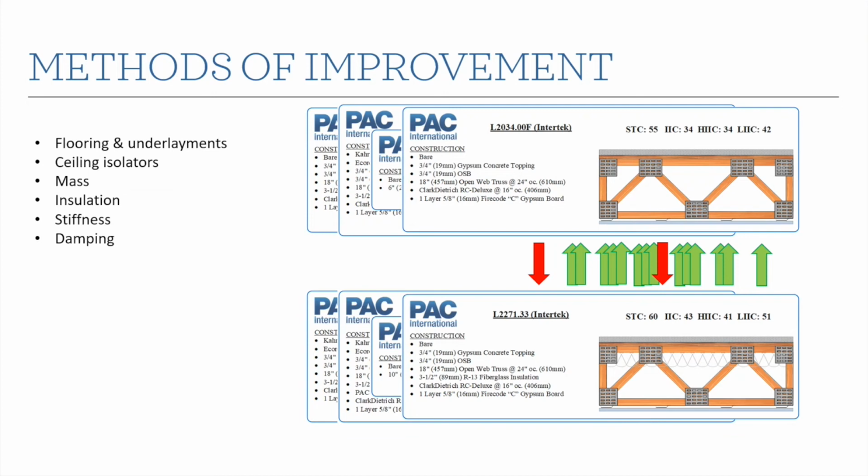And just a note, especially for the acoustical consultants on here: for the STC ratings, this comparison is limited because of flanking limitations at the lab. Believe it or not, even as we start to get up to just STC 60, we start running into contributions from laboratory flanking.